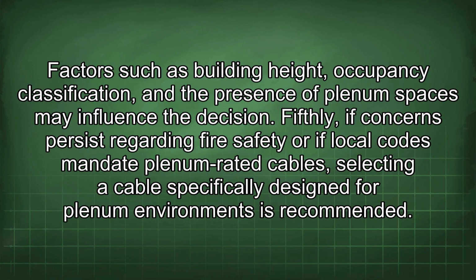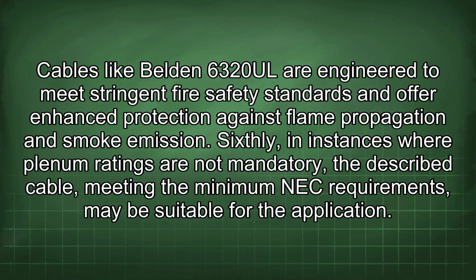Fifthly, if concerns persist regarding fire safety or if local codes mandate plenum-rated cables, selecting a cable specifically designed for plenum environments is recommended. Cables like Belden 6320 UL are engineered to meet stringent fire safety standards and offer enhanced protection against flame propagation and smoke emission.